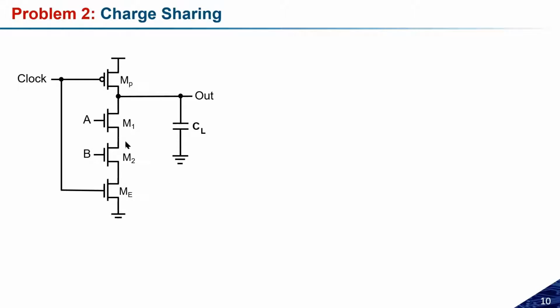So if the circuit is in the pre-charge mode, I need to keep the clock at logic 0. And one more important thing: all the internal nodes must have some capacitance, because we have already studied in the RC model that each node can offer some node capacitance. So let us try to draw those load capacitances first, and then we can discuss later on.